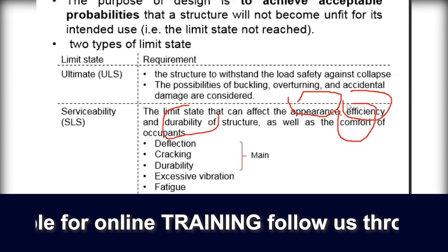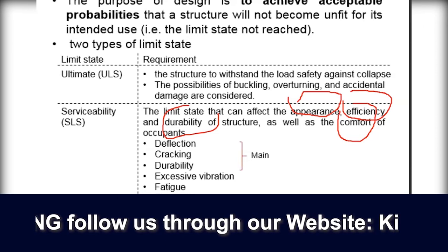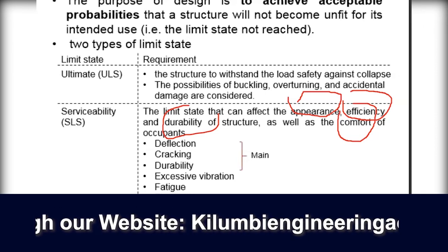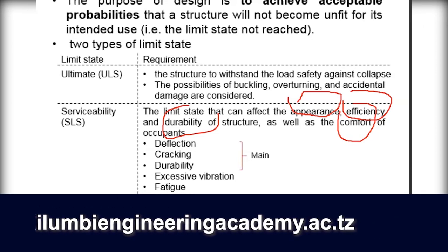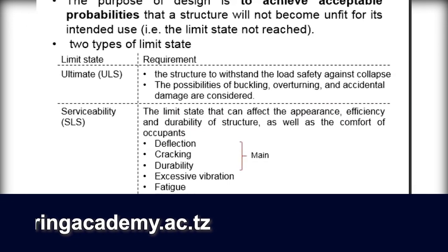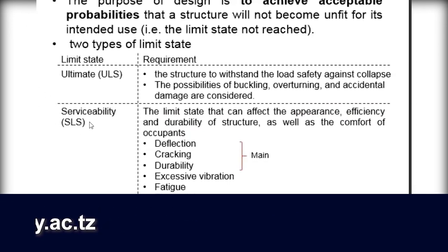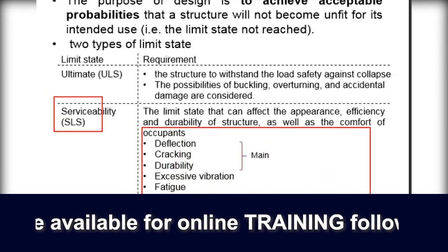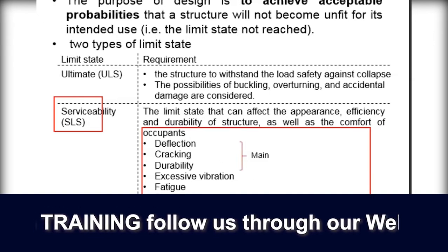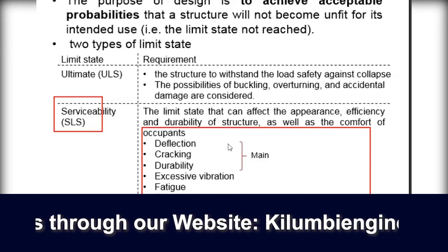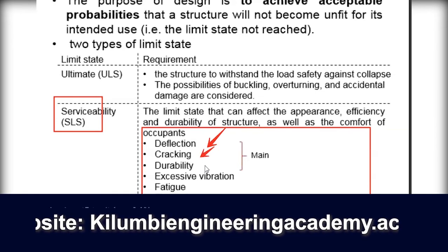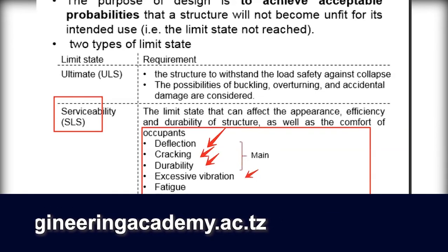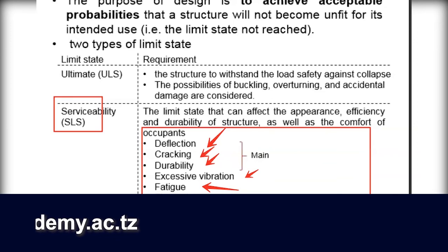So generally, once you consider the serviceability limit state, these factors should be considered in your design to be safe: the deflection check, cracking, durability, excessive vibration, fatigue condition, fire resistance, and others.